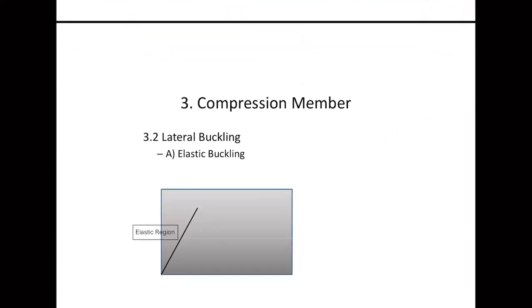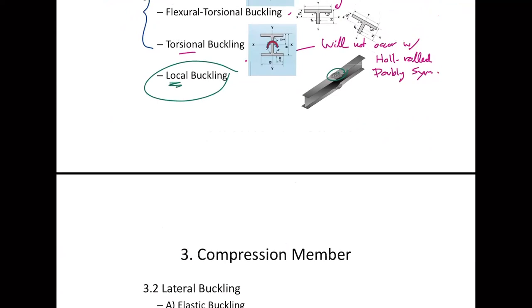Yes, please. According to the video, I see that the support, the pin support, it rotates about its weaker axis. But what if we install? It's not possible. Maybe it's a problem with installation, because that's why I sort of assumed that the second video clip was done like for the term project, student term project, because when we talk about this, the ability to rotate in both axes must be equal. Okay, and let's say you can imagine your plastic ruler and you apply compression, it's impossible that it will buckle in another axis, in the strong axis. Can you imagine that?